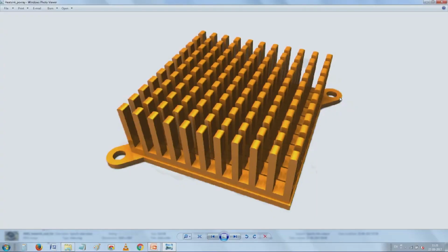Do you just need to put force, or underneath that do you put some thermal paste and leave it at that, or use the paste itself as a bonding material? Can you make a thermally conductive setting adhesive? So, you have these epoxies which are also thermally conducting, plus they set. So, the forces are a little low, and then you can avoid the tabs which are present there.